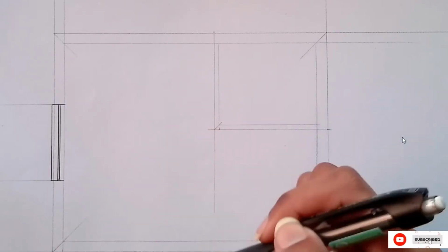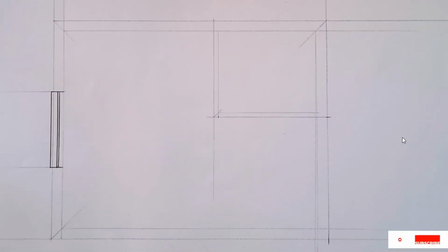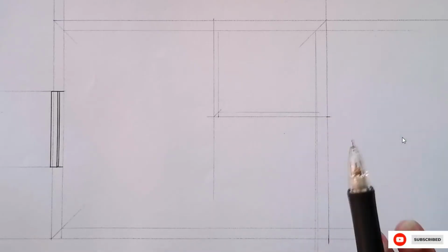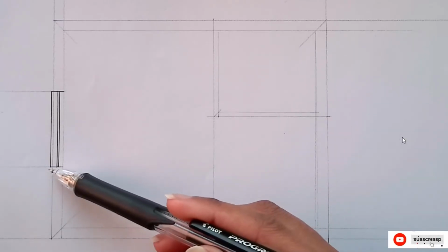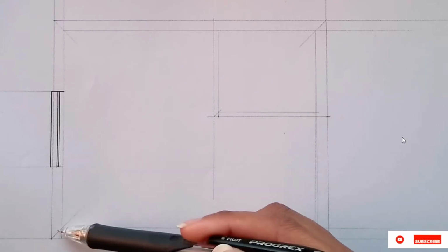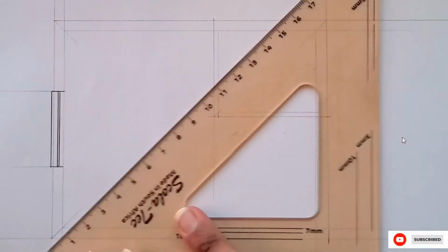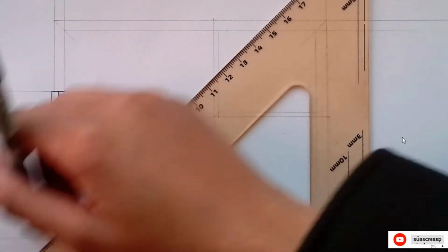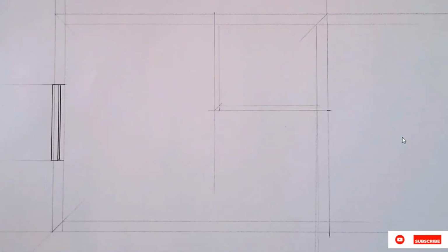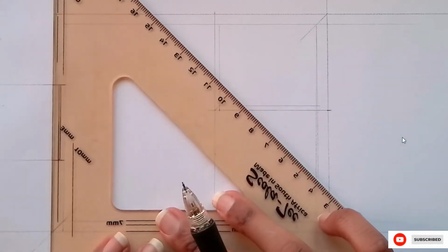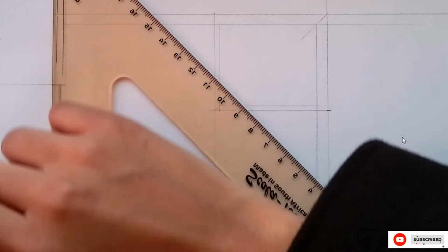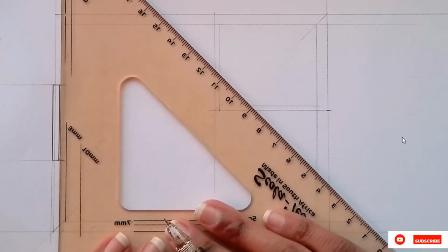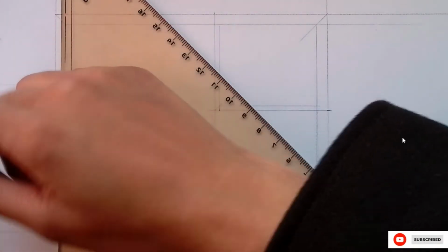So this window is what's going to get us the rest of the windows that are on this floor plan. There's about, I think, 3 more that we need to do. We have 1 here, and we have 2 on this side. So I'm going to now project all these to this 45-degree line. I'm going to extend my 45-degree line here. Once it's extended, I'm going to project the window sill and my 2 lines for the frame.